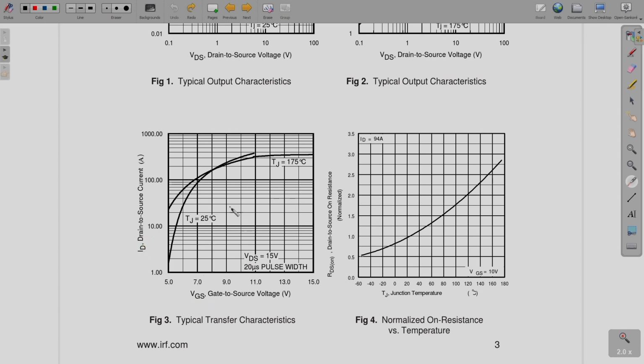And again what we see here is that this is the threshold, and then as this voltage increases, what is the point when your drain current starts to build up. So, from here also you get an idea of how much is the gate to source voltage that you should be applying. So you get the idea of your QG, you get the idea of VGS, and some equations I have given you, and plus you also get an idea of RG, what is given in the data sheet. So, from all these different values you get an estimate of what is the gate drive requirement.